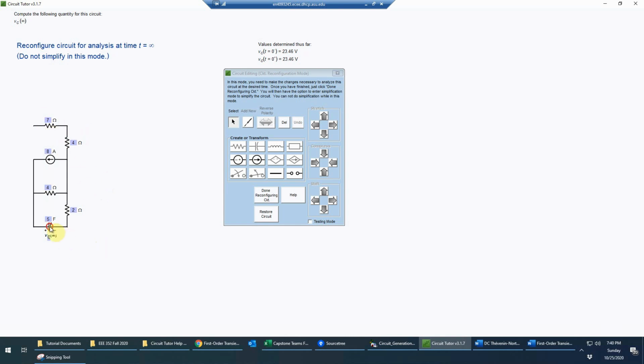Okay, and then I also want to change the capacitor. And again, since I'm going to be in steady state, remember that I equals C dV/dt. See, at t equals infinity, any transient will have had lots of time to die out. And as long as it's a stable circuit, and frankly, any circuit that doesn't have a dependent source has to be stable, then we don't really need to worry about that. And therefore, we will be in steady state. And since I equals C dV/dt, the dV/dt clearly has to be 0, which means the current has to be 0. So once again, just like at 0 minus, this is going to be an open circuit.